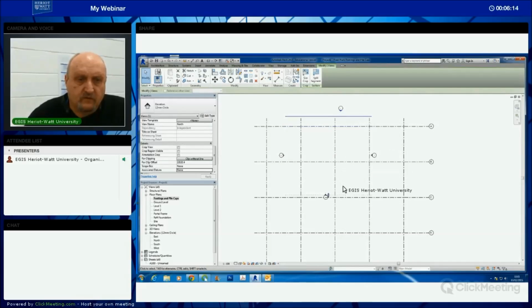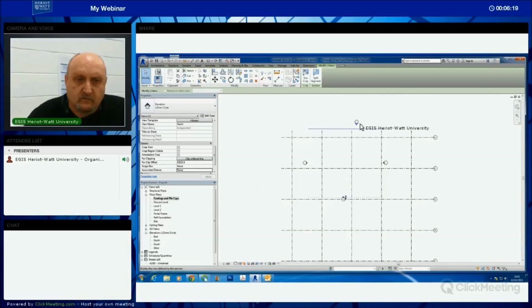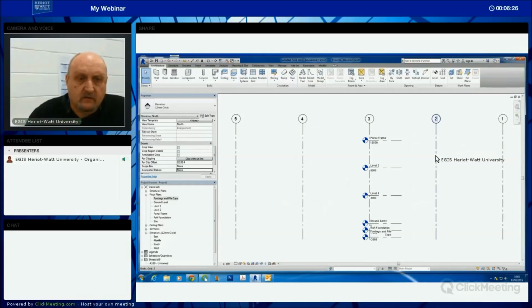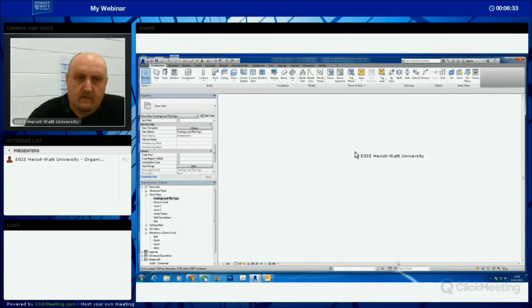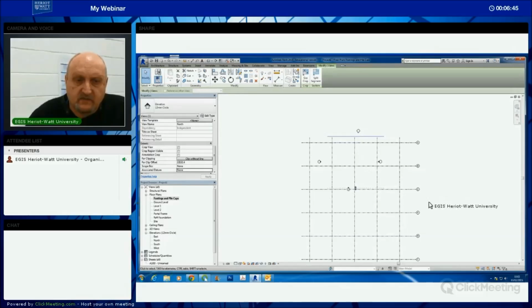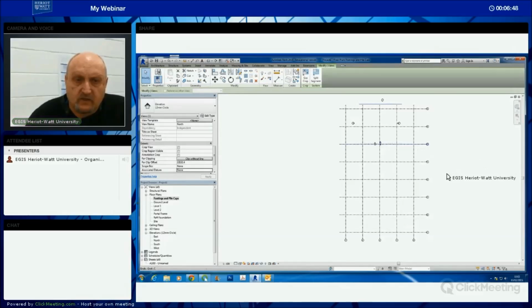Now this is the opening view and this is the closing view. So if we were to look at this as north, obviously, well maybe not obviously, but it's north, and if we were to double click on this, it would take us to the view of what will be this structure from the north elevation. So I want to make sure that when I click on it and look at this structure from its north elevation, I can see the beginning of it using this line here, and I can also see the end of it. Because if this is a glass wall, I want to see it all the way through the building. I don't want the view to stop here.